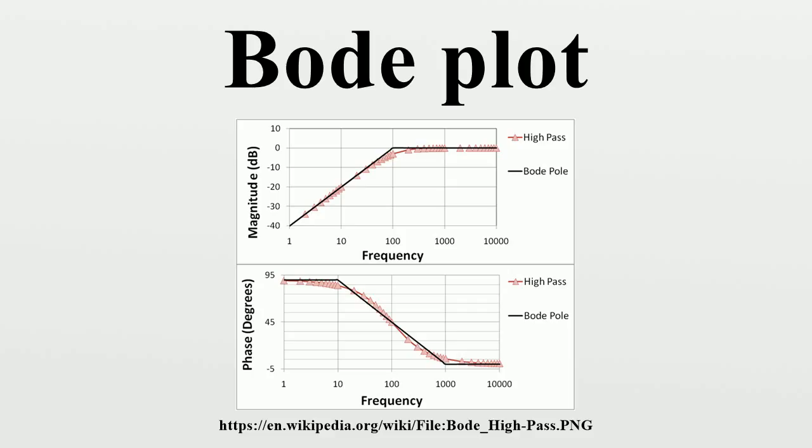Simple plots can even be predicted without drawing them. The approximation can be taken further by correcting the value at each cutoff frequency. The plot is then called a corrected Bode plot. Frequency response and Bode plot.